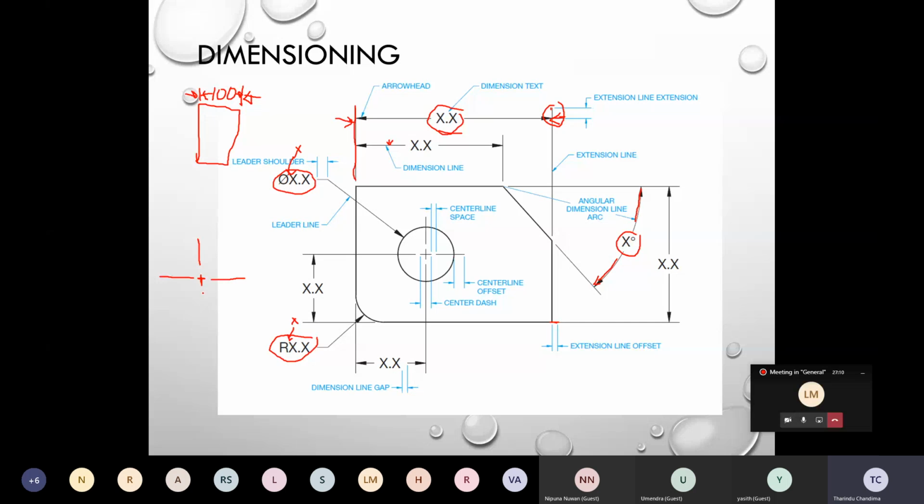Then you have a longer line and a longer line there, right? If you place a longer line, shorter line, and in the vertical side a shorter line here and a longer line here, like this, then it's wrong. You have to make sure that 2 short lines intersect at the center, right? And also there should be a space between this shorter line and longer line, right?